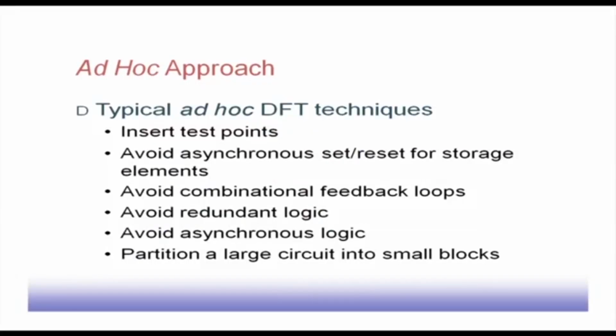We can detect more, because the faults will become more non-equivalent. As a result, they can be detected. However, this redundant logic removal is not always advisable, because designers, to avoid hazards and glitches, may like to put some extra gates in the circuit which are actually redundant, but that helps avoid them. So though test engineers will ask for that, the design engineers may be telling the other way.